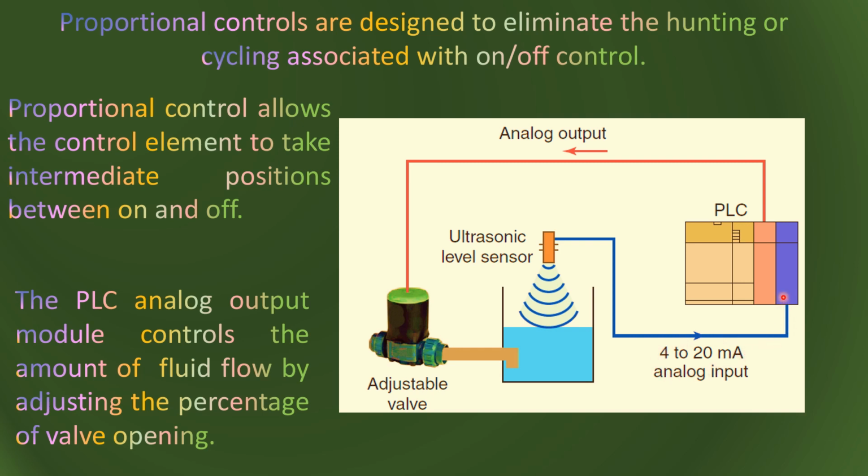When we come very close to the PLC, we convert this signal to the voltage. Nowadays, people are sending this signal using optical signals with optical fiber, and also with network connected systems. These signals are sent as digital signals, and different protocols are available to convert the level to those signals. It can be a digital signal, an analog signal in the form of current, an optical signal, or one can send it by Wi-Fi or XBee signal. So we can send it in different ways to the PLC.